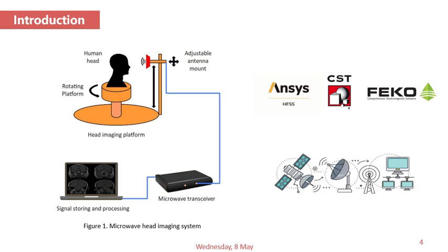However, as the demand for high performance in these applications has increased, there is a need for miniaturization techniques that maintain the radiation pattern stability of planar antennas. On the other side, the theory of characteristic modes has emerged as a powerful tool for optimizing the performance of antennas. It is based on the idea that the field of an antenna can be represented as a superposition of different modes, each one with its own characteristic properties. It was originally developed by Garbacz and refined by Mautz and Harrington.